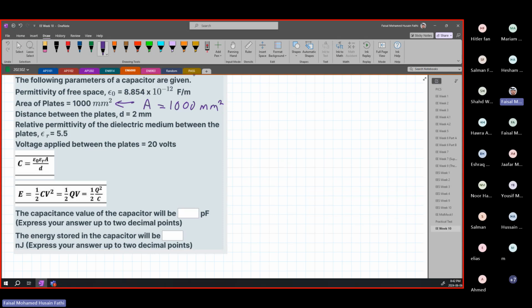How do you do that? You are going to multiply up and down. What do we want it in? Meters. What do you want to change it from? Millimeters. All right. 1 meter has 1000 millimeters, right? However, this is meters to millimeters. We want it squared, so we have to square everything up and down. If you notice, the millimeters squared will cancel with the millimeters squared.